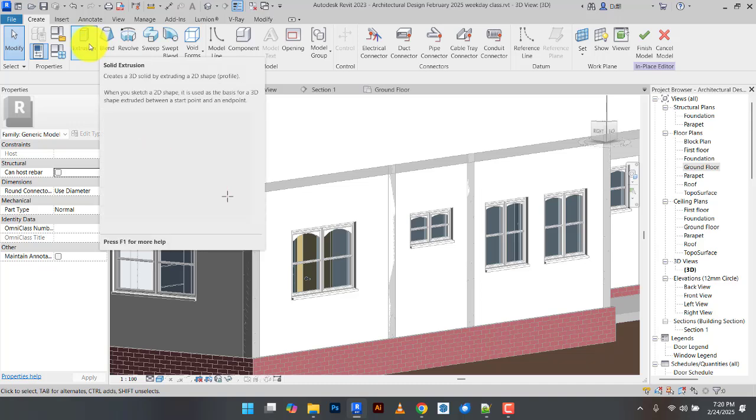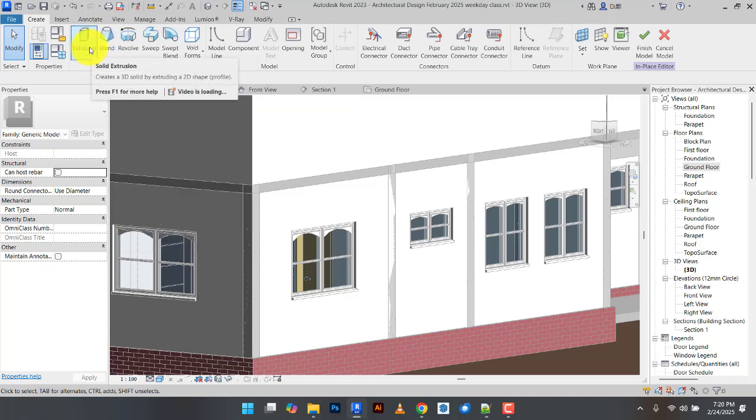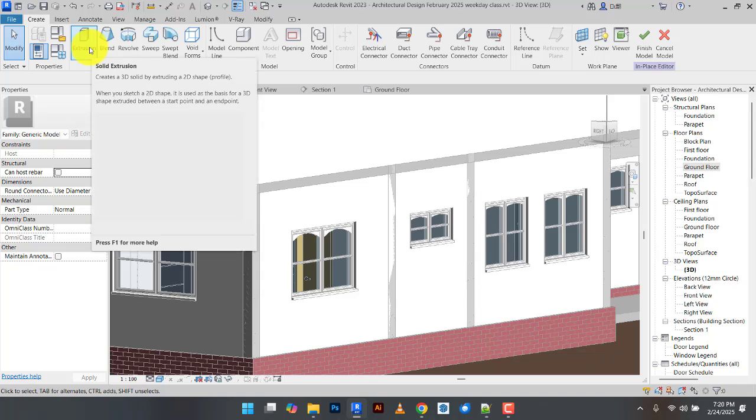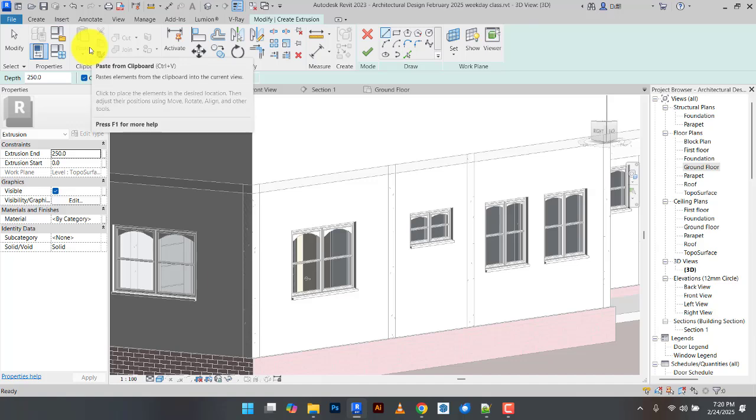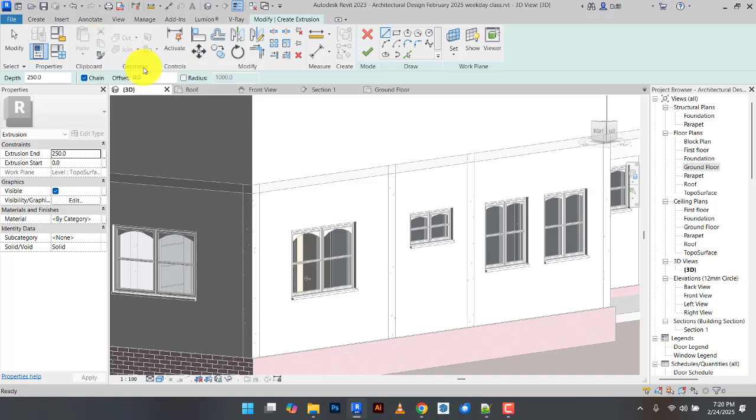You click on it. Now we are doing modeling. Okay, so let's look at the example. You draw your shape, and there's also extrusion for it. So you click on extrusion. With extrusion, you have to draw it on the surface you want the extrusion to happen, just like the model test. When we started drawing, it went down and put it on the surface. This one, if you draw it right now, it will fall down because the work plane is down.